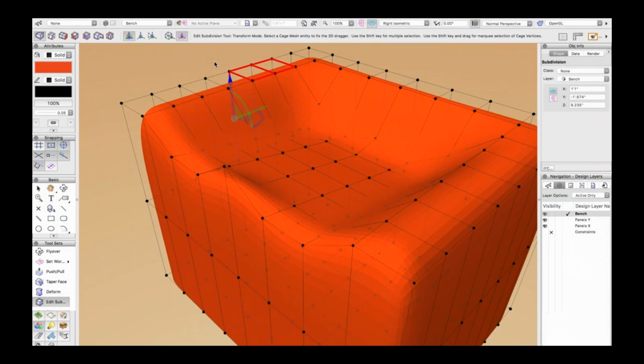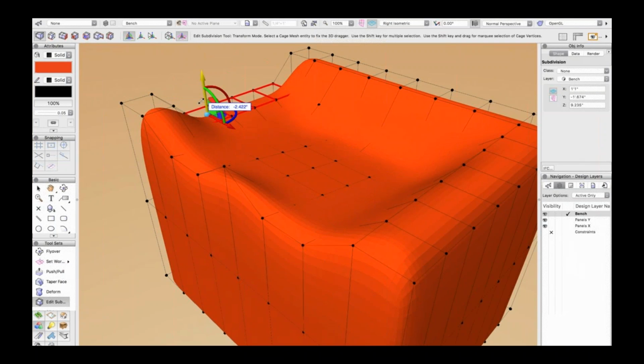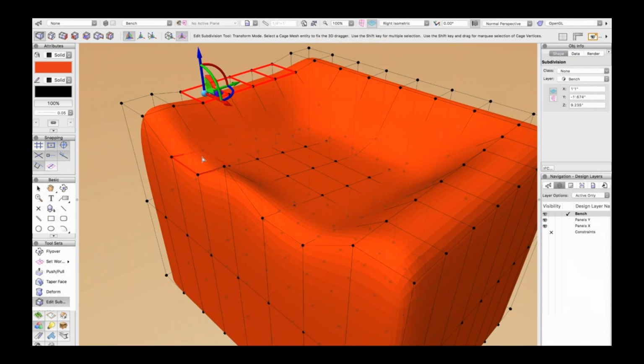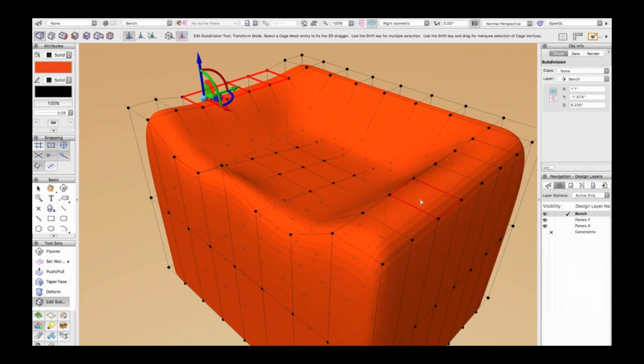That is an effect of the snapping palette. Now, when you're using the Subdivision Modeling tool, you can turn off all of your snaps. That is an option. But there's two different methods there. If you're going to use constraints, as I've done in creating kind of this constraining object that I want my object to fit within, you may actually want your snaps to be active. Well, if you're just creating something freeform that really doesn't have constraints and it's just more of a conceptual idea, then you could essentially turn off all your snaps.